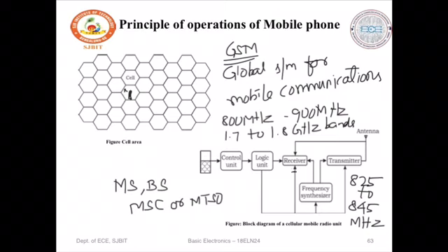The receiver, which is a cellular receiver, consists of an RF amplifier, FM demodulator and the filter. An RF amplifier boosts the level of the received cell signal. The receiver frequency range is 870.03 MHz to 889.98 MHz.